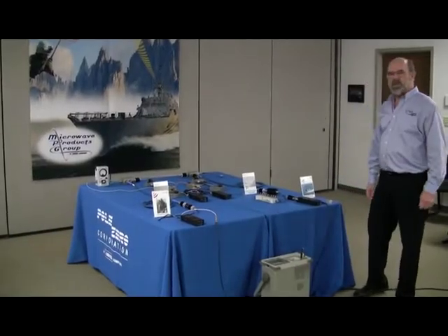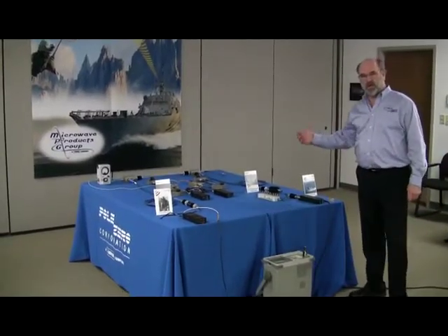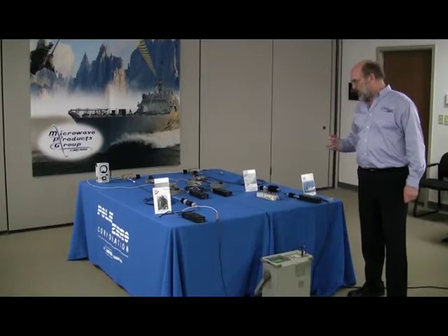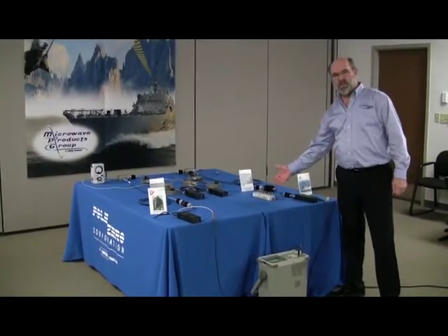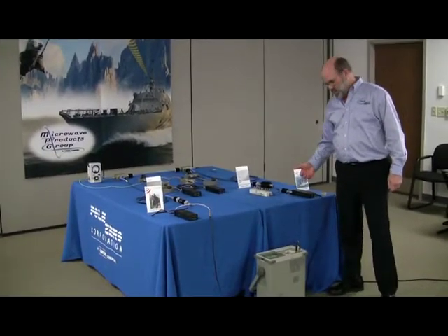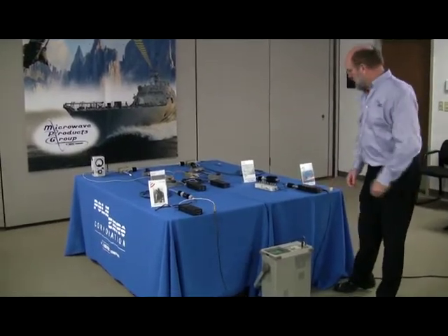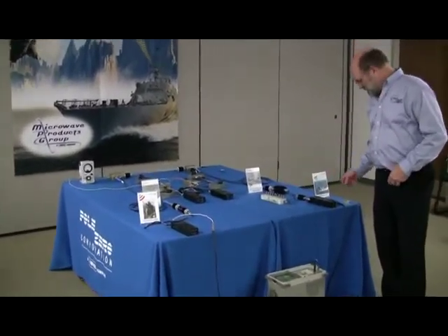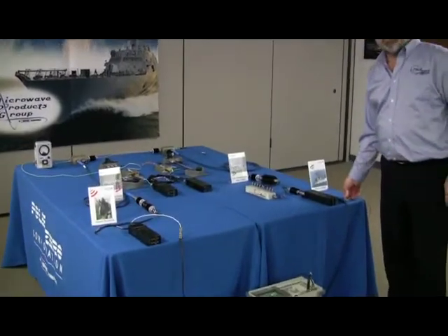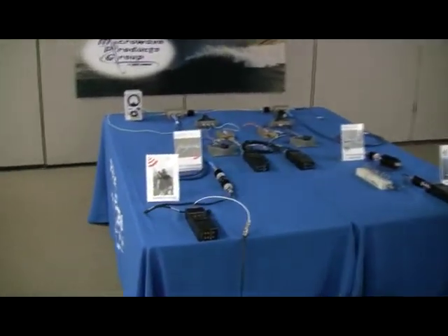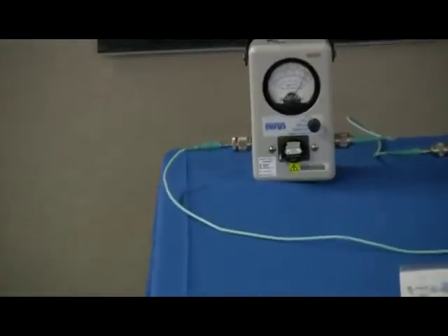All right, now we'll look at the case where the Cosite mitigation units are in the circuitry. If you recall, previously we had 20 dB of attenuation on the uplink transmitter, which yielded 12 dB of SINAD. We've left the 20 dB in place, but now again we have the Cosite mitigation units operating. So as I key it, we find that we do have our 5 watts of output power for the downlink transmitter, but the 12 dB we had for SINAD now is much better. It's again like the high 20s, reflective of the fact that we're mitigating some of the Cosite interference.